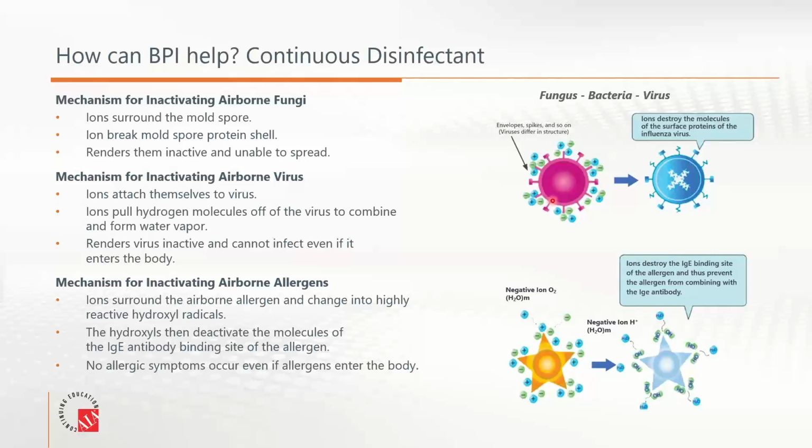And that's the unique thing about bipolar ionization, but specifically about dielectric barrier discharge. There's a lot of technologies out there, and you've heard them: the needlepoint bipolar ionization, the PCOs, the PHIs. There's all kinds of different technologies, but the unique thing about DBD technology, and that's the tube, is that you're creating a high voltage differential. That high voltage differential allows those ions, those super ions, to be created, and they're the ones that are significant in the fungus and bacteria kill.